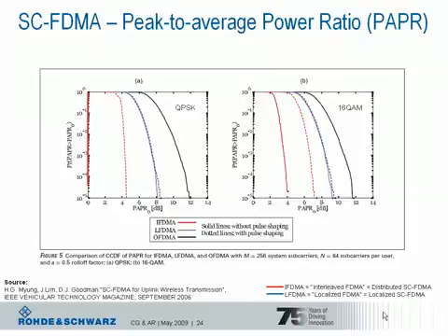In difference to 2G and 3G, there's no filter definition in LTE, meaning this is open to the design engineers. Just the defined in-channel requirements, for example modulation quality measured with the EVM, and out-of-channel requirements, for example adjacent channel leakage power ratio or spectrum emission mask, need to be passed by the transmitter design. In this simulation, a root raised cosine filter was used with a roll-off factor of 0.5. As we can see, the crest factor for OFDM is constant at around 12 dB, which is comparable to WiMAX, and it is independent from the modulation scheme and the used filter.